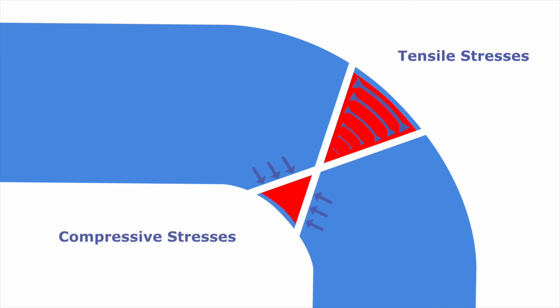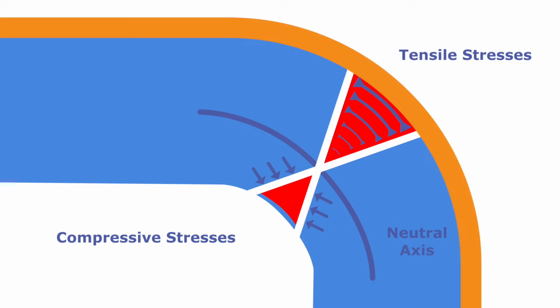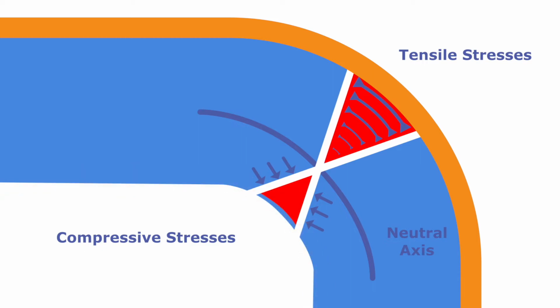Think of coil-coated metallic-coated steel and aluminum from a side view as being composed of a large number of very thin layers of metal. The layer where the compression ends and stretching begins is called the neutral axis, or the neutral layer. The length of the neutral layer does not change during the bending operation, whereas the outer layer gets longer and stretches, and the inner layer gets shorter and compresses. We are most interested in the outer layer and the stresses involved in the stretching process, the cracking that may occur, and the possible loss of adhesion.